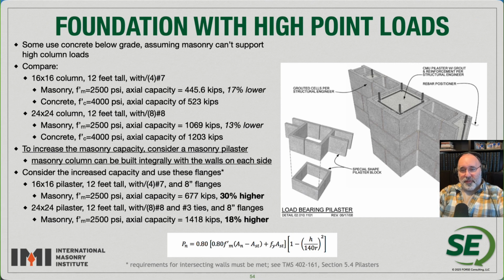Another comment or concern that people have had is, again, if you have a building, maybe it is going to be a taller building that has say a post and frame kind of construction or post and beam construction. Looking at when we get below grade, I think it's always important to recognize that you do have masonry piers that are available. They actually have blocks that are made, special blocks for pilasters, but certainly you could just use standard, say, 8-inch blocks to make masonry pilasters. And it's really good to recognize some of the different capacities that you can utilize with masonry pilasters.